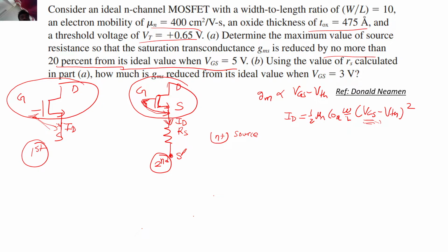You are applying maybe the same voltage at S dash and S. So whatever voltage you apply goes directly to the source terminal, but something will happen over here and some voltage will come across. Now I am asking you, in which case will the MOSFET get a larger VGS, case number one or case number two?